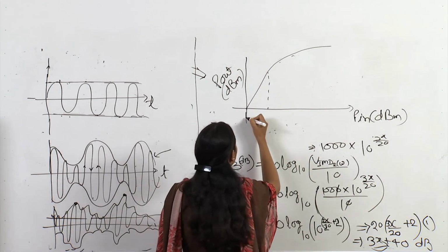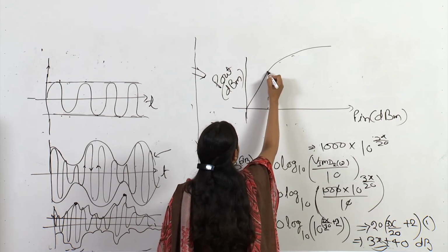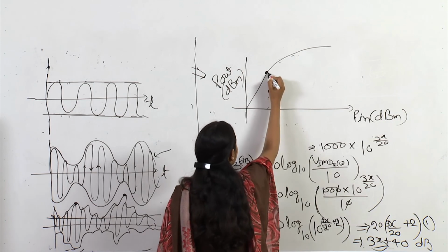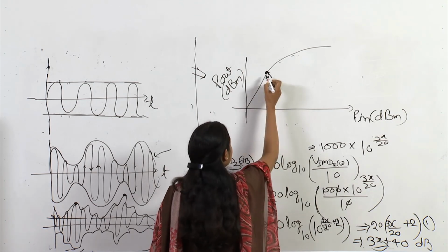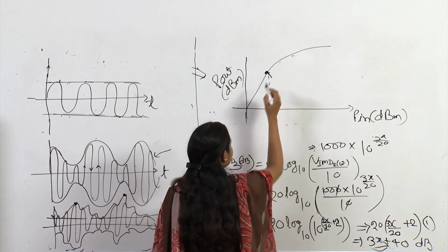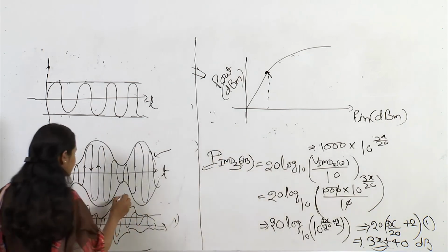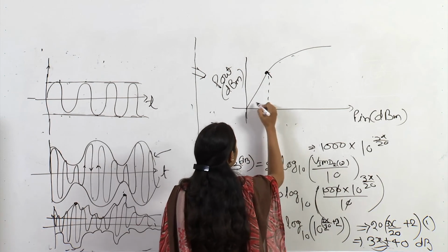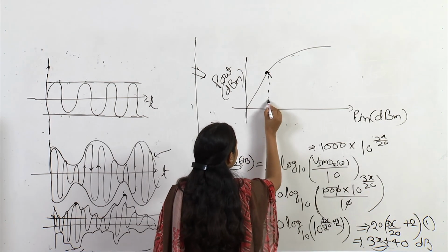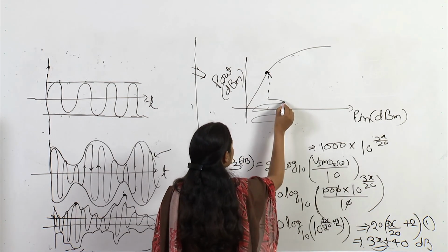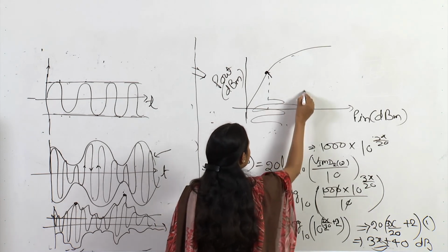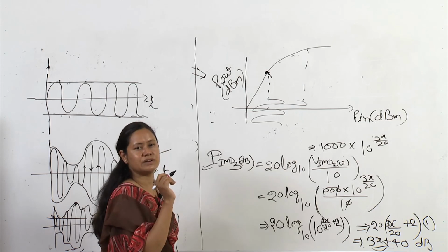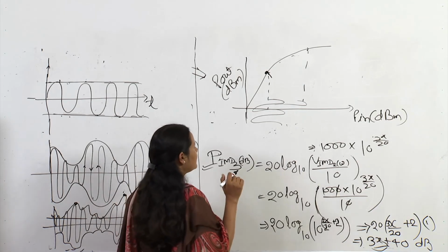So, I want to drive this amplifier so that it is not that much distorted. If my average power lies here, then my signal average power is here, but because the peak is going to other values, when we apply this signal it is not constant and some of the peaks can even go here. So, in those cases some of the IMD components will be generated very easily.